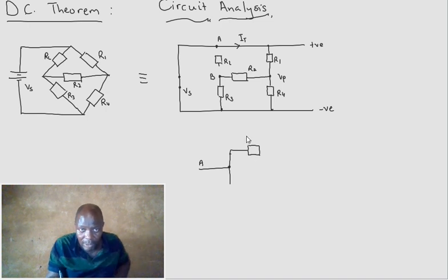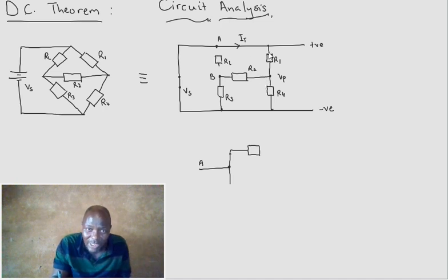But notice this. I won't start with R1. Why? It's going to take me to a lot of places. Notice how, leaving A, this whole line has been joined together, so this is all A. Now, I could go straight to B via R3. Since this takes me straight to B, I'd rather start with that. So one route is straight from A via R3 to B. However, there is another way of going through, and this is the first one there, R1.